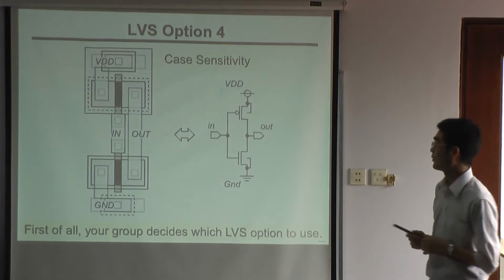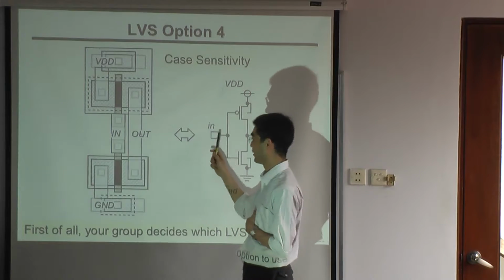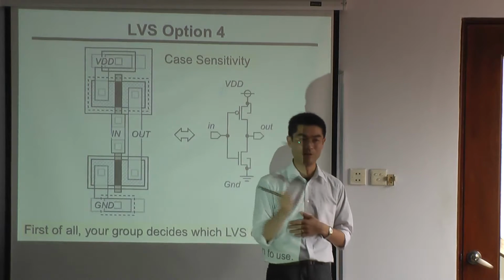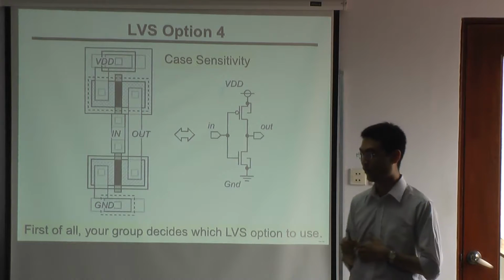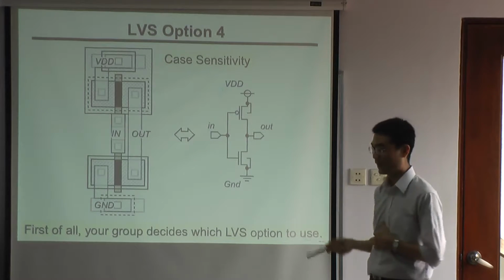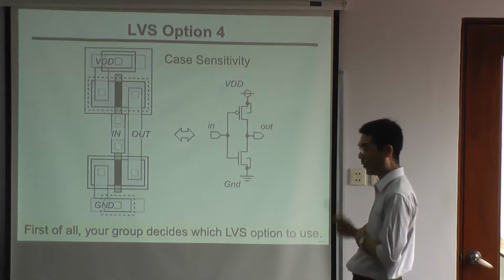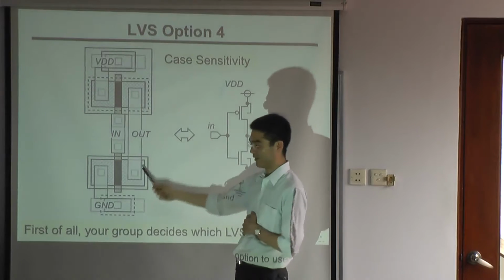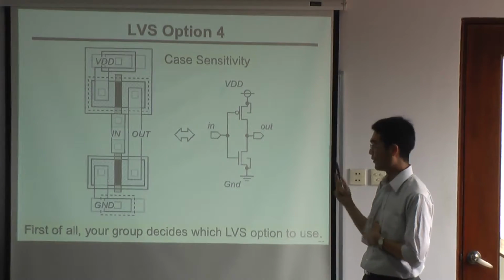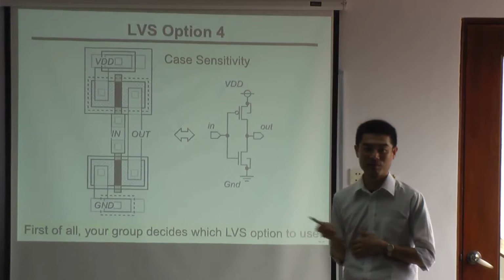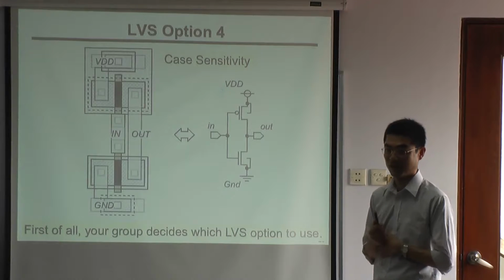And another LVS option is case sensitivity. This is very, very important. I recommend you turn case sensitivity on, and then this is an error. That's my recommendation, but of course this depends on your team. So your team will decide before starting your design.